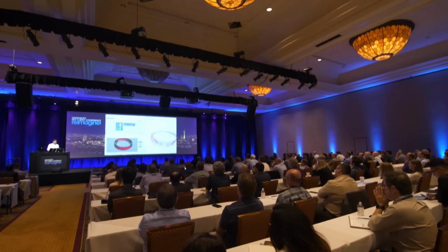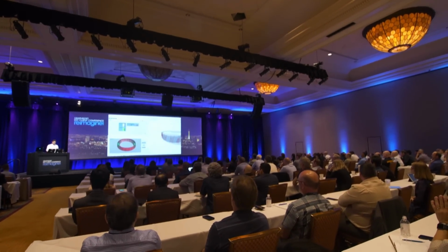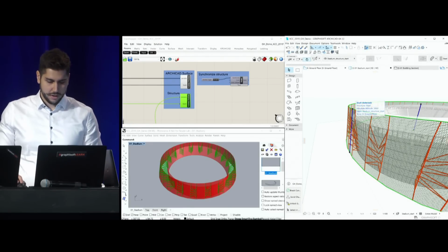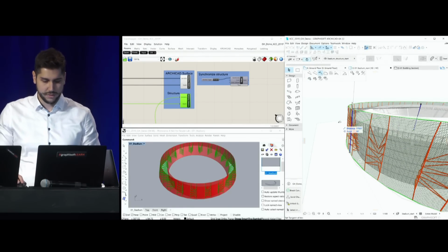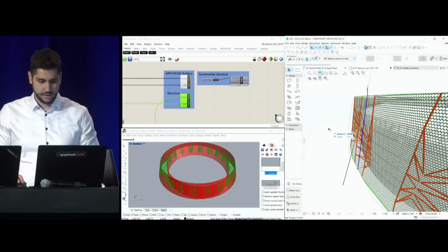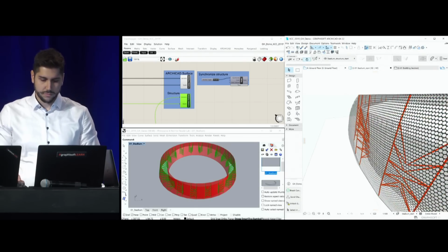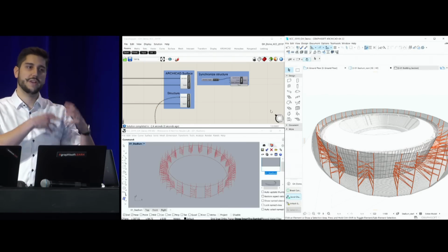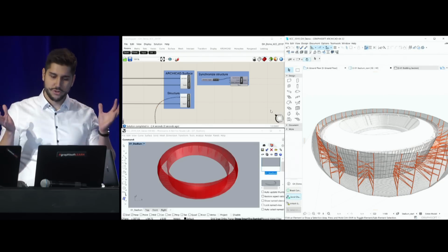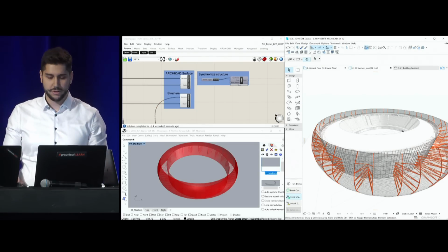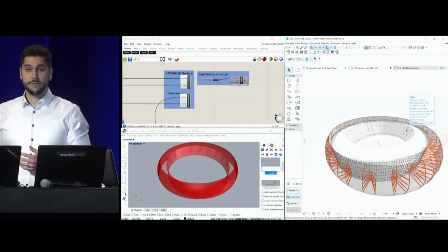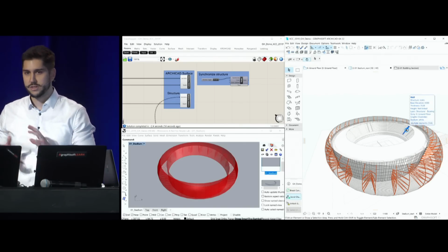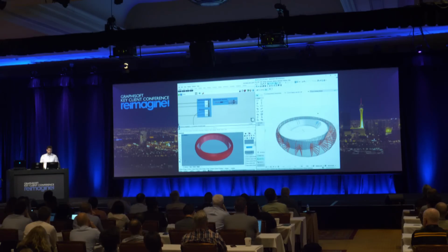But as I mentioned, we are in the early design phase, which means that the building design goes through a lot of changes. For example, I would like to bulge and curve the profile of the external shell of the ARCHICAD shell here. Something like this. So now I change the surface geometry of the ARCHICAD element, and by sending the changes to Rhino and Grasshopper, the code recalculates the structure between them and bulges it according to the surface geometry. This allows you to discover more design options, experiment more with the building envelope and try out different variations.